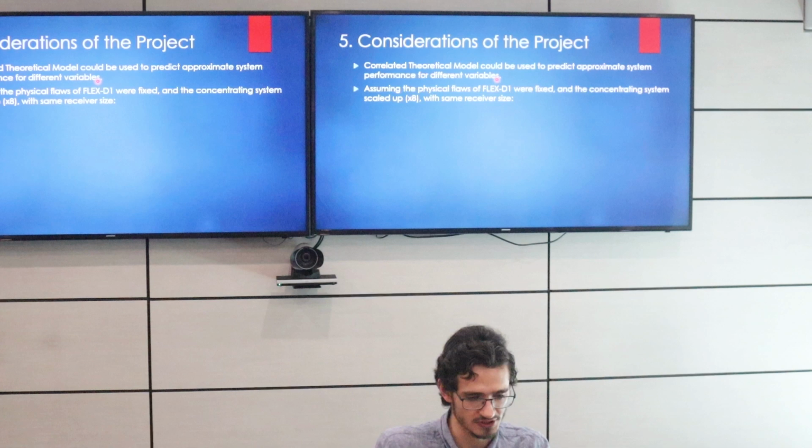And with this is then given the following recommendations: to develop methods to clean the lenses and mirrors effectively, to construct a solid conduction core receiver, and this is to remove the thermal contact resistance in it, to stabilize the system, such as using a stronger structure, to improve the theoretical model by creating mathematical correlations that are developed for the FFD receiver, and then to do a more in-depth feasibility study on the improved system.